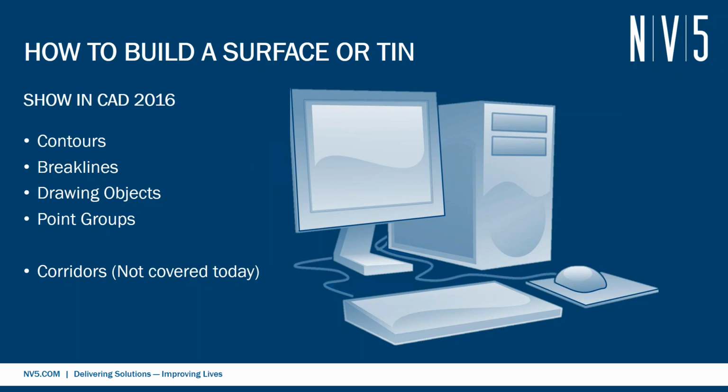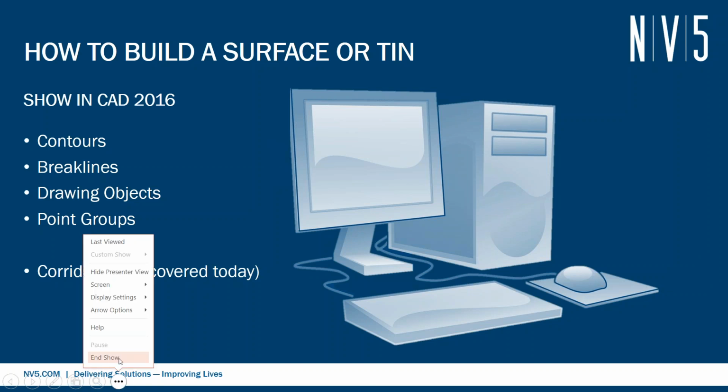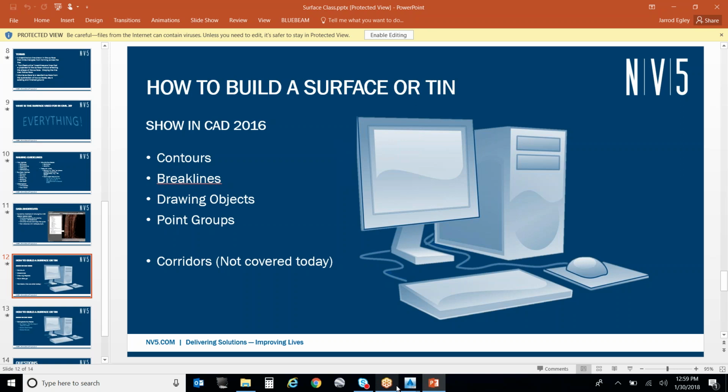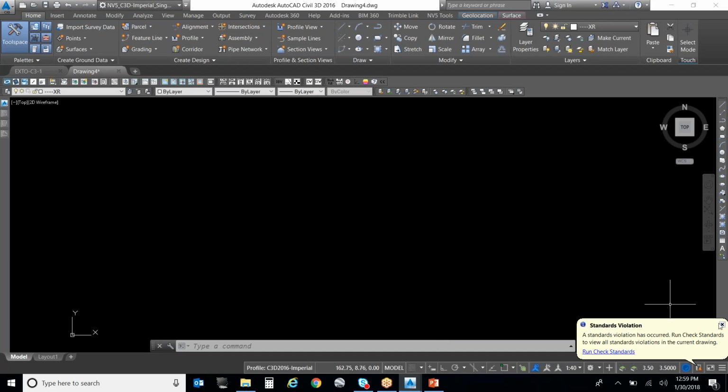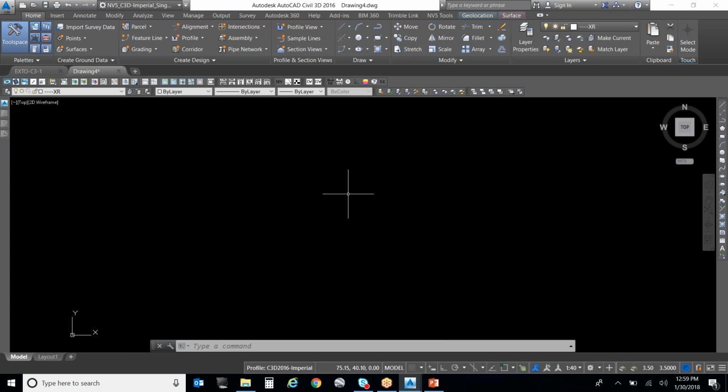Yes, Amy. I just have a comment. No, I said questions. For everyone to know, I get asked a lot for, oh, can you get me contours for an extra area or something, or tiny topo for this? And I always try to emphasize it, but I know I'm not the only one creating stuff from GIS, that the GIS topo that we have available doesn't fall into any of those categories. It should never be used for design. Not everyone understands that. That is like a hydrology level of this is the direction water flows type of thing. Be very careful about GIS contours.